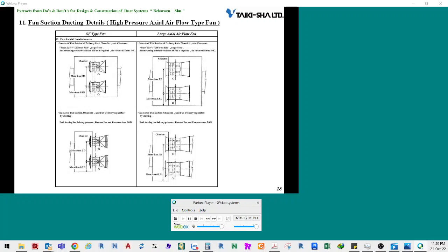Ensure a distance of 0.8 D between the center and chamber walls of the fans, and 2 D between each fan. If some fans stop operating due to some reasons, such as problems when operating a number of units, dampers must be attached to individual extension cones or rectangle to round ducts to prevent the air from flowing backwards. If ducts are separately arranged on the suction side, select fans suitable for individual duct systems.